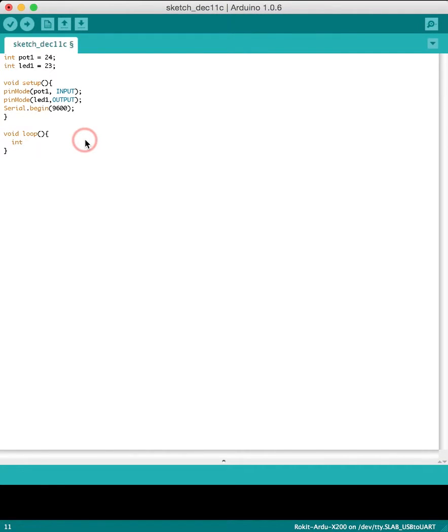So this is done by doing this. Int data, creating a variable to place all the numbers from the potentiometer. And then we'll include a brightness level that is being mapped based off what you're getting from the potentiometer. So here's the mapping data. We're going to map whatever data we are getting from the potentiometer onto the LED.